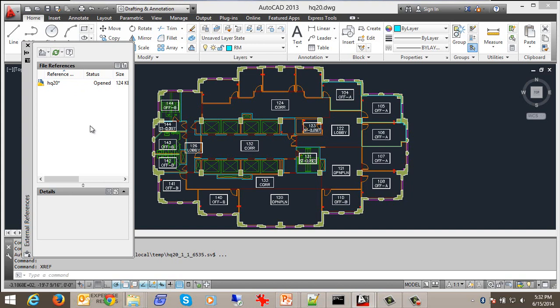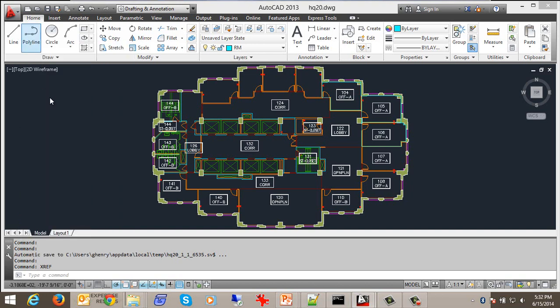So this is where you can go in and assign, on this floor plan, your architectural and your furniture, if this is your ARCHIBUS drawing, and XREF them or overlay them on top into the corresponding drawing. ARCHIBUS does allow XREFs to be used within the drawings, so this is definitely something you may consider as part of the process. ARCHIBUS does handle XREFs very well. So that's the XREF concept.